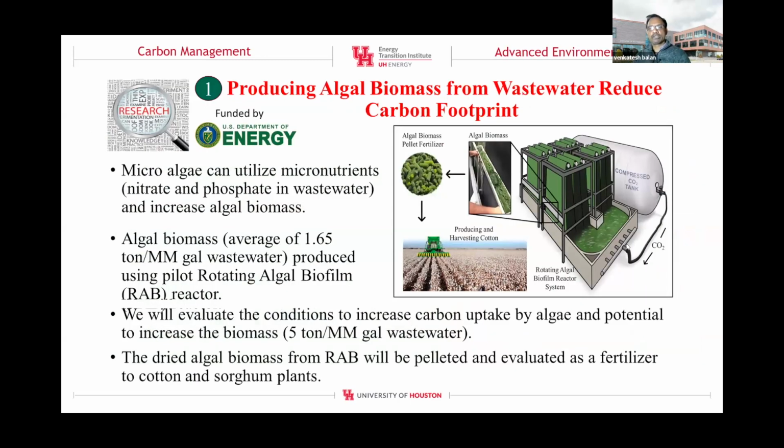So I gave some introduction, and I'm going to jump into various applications, how we can make some money out of this. We have got some funding from the Department of Energy to evaluate this algal biomass generated from a wastewater treatment facility. We propose to collect the biomass, densify it, and then use it as a fertilizer for growing cotton plants. Originally, when they were doing this RAB system, they were not impregnating any CO2. So we propose to bubble CO2 and demonstrate that we can increase the algal biomass productivity by threefold. That's some of the ongoing work we're doing right now.